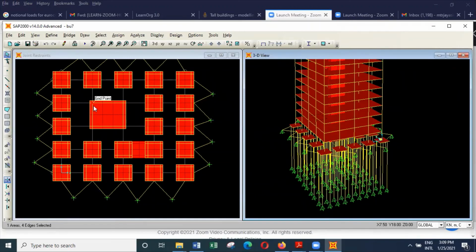So if you have predominantly end-bearing piles, then you can go for something like 2.5 times diameters. Whereas if you are mobilizing significant skin friction, then better to go for something like 3 times diameters as well. So it's up to you. But in this area, sometimes the 1 meter diameter pile may not be sufficient. But for the time being, I have allocated 1 meter diameter piles.